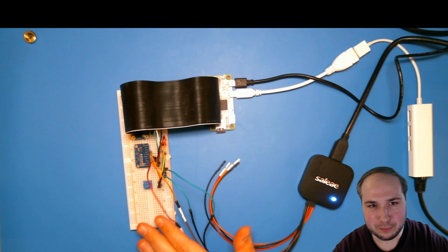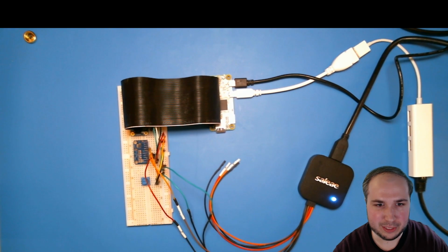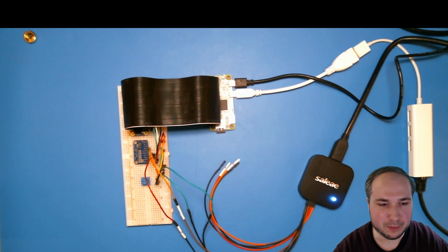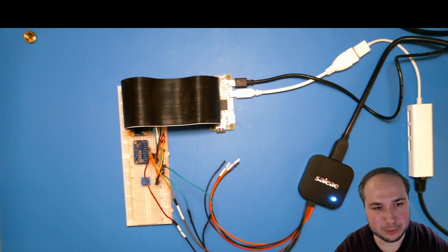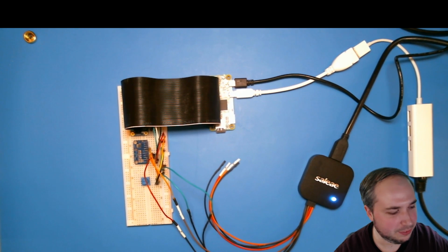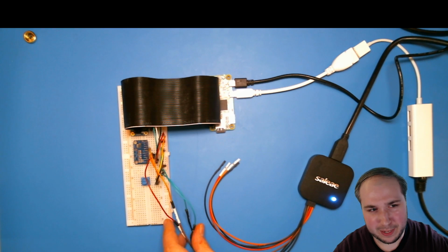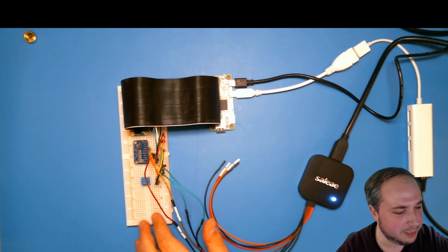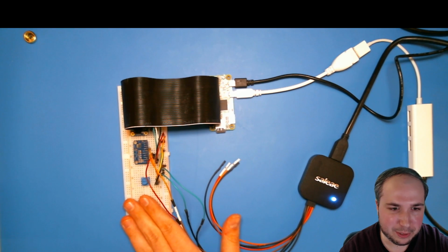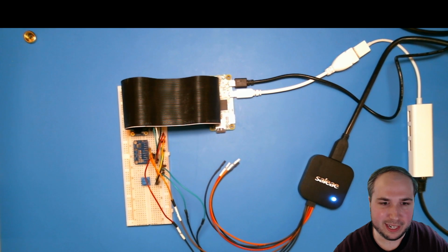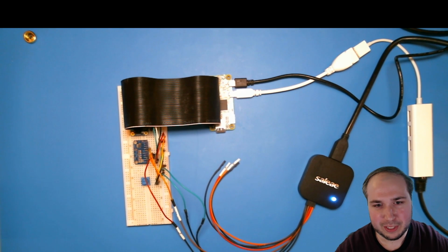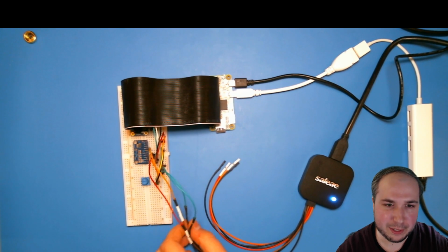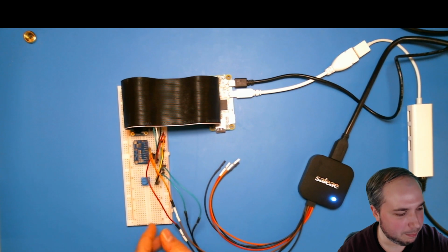And it just gives you a digital value, so it'll convert that analog value into a number. This one's 16-bit, so it goes from 0 to 65536. Well, actually, it's a signed value, so it's like 32,767. But either way, it gives you a digital value that you can use to interpret that analog signal. So if it's a temperature sensor, you could say a high value probably equates to a higher temperature.